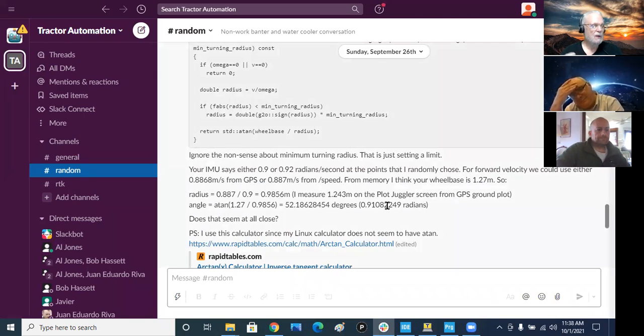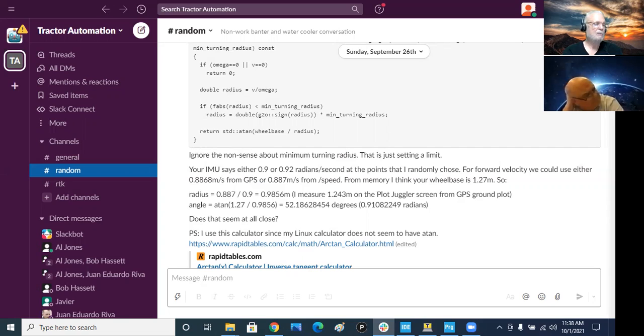So it only tells you at a single point what it thinks this quote angle is. I don't know if that angle is technically the vehicle angle that it's measuring, or if it matches wheel odometry, and mine has wheel odometry. It also tells you the angle as you're turning. I don't know if those two numbers match, or if either will match what you'd put in for a steer angle request. I modified my code and was at the point where I could take it out and drive it to verify that. Then I got distracted trying to move the GPS location around.